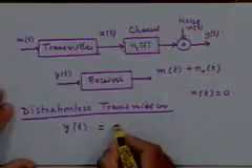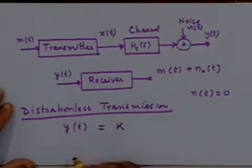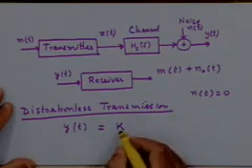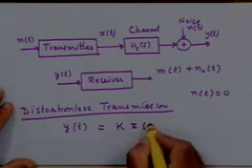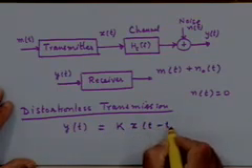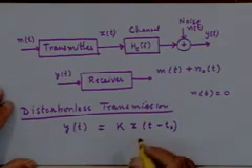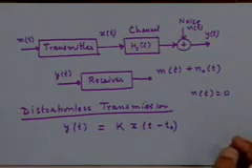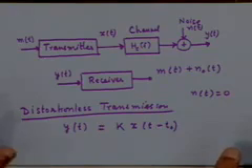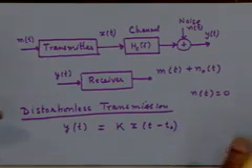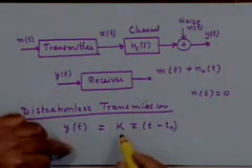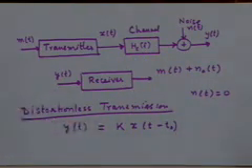So ideally speaking, by distortionless transmission we mean that the received signal y(t) is some constant k times x(t), delayed by some amount t0. So this is the condition for distortionless transmission. If your channel only introduces a scaling factor and a delay, it's an ideal channel. Nothing could be better. Then the channel is a very friendly channel, and that's the kind of channel I'm looking for physically.